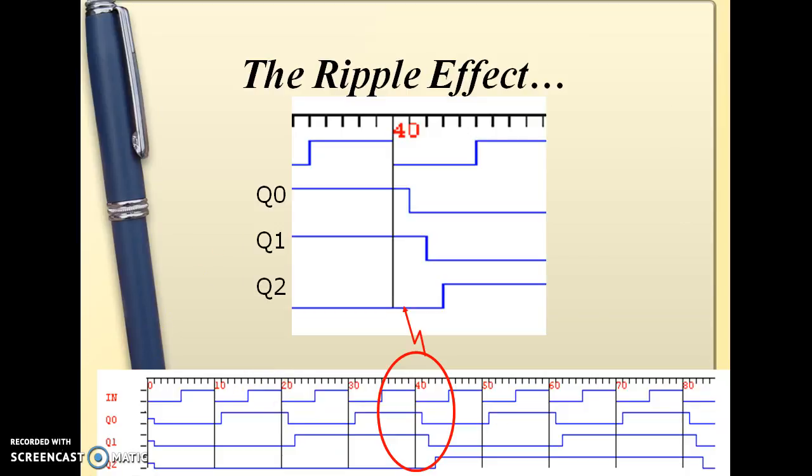For a 3-bit counter, when the first clock edge hits the negative edge, the Q0 output will take some time to respond. When this changes from positive to negative, Q1 will take some more time like this. So we can see that the delay is accumulating from Q0 to Q1. Again, when Q1 hits the negative edge, Q2 will take some more time to respond. So all these delays are cumulative.